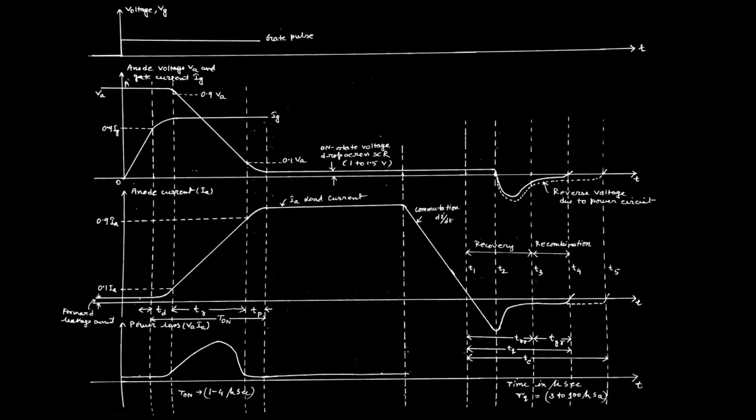It is due to the anode current movement over the cross-sectional area of the cathode, and due to uneven distribution of the gate, the anode current initially starts moving in a narrow region of the cathode, which is defined by TD. Then in the rise time the anode current starts spreading across the cathode cross-section, but it is not able to cover the entire cross-sectional area.